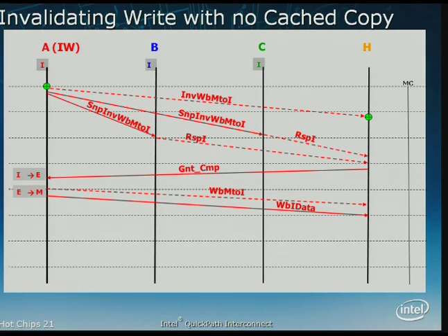With this flow and one other rule, I have a coherent IOH that I never have to snoop. You heard me previously say that snoops are either sent, spawned, or implied. So with this particular flow, I have no snoop filter, no directory, no directory cache, but I still maintain coherency, and I send those snoops to the IOH.